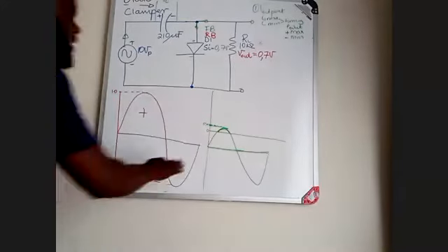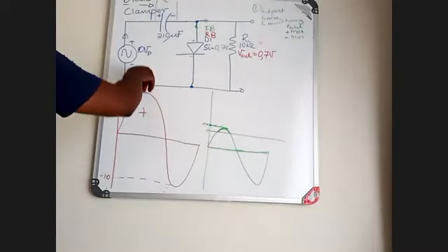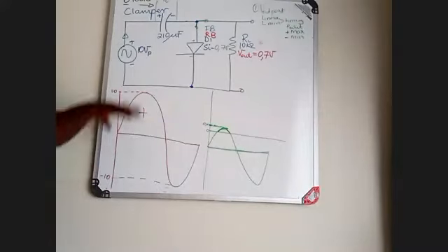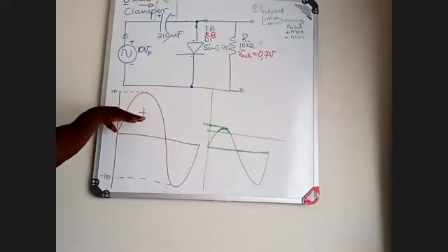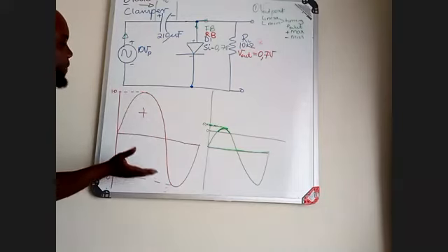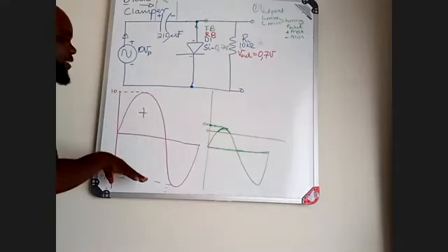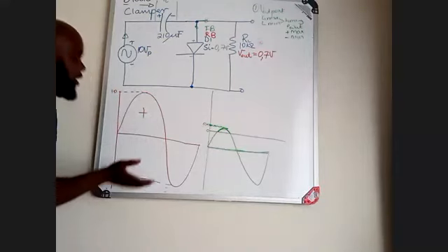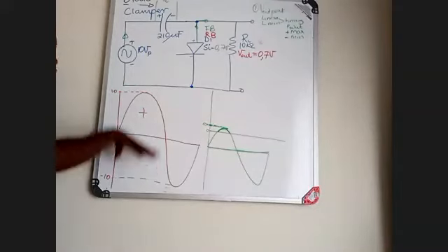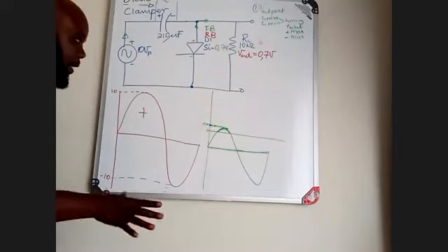Since I can see that only the portion of the maximum is positive, the graph will shift downward. Most of your graph is no longer half positive, half negative, but about 90% negative, 10% positive, which means it has shifted downward. Because it has shifted downward, it becomes your negative clamper circuit.